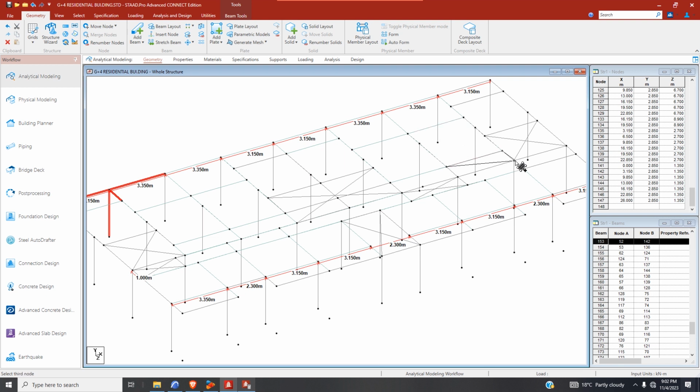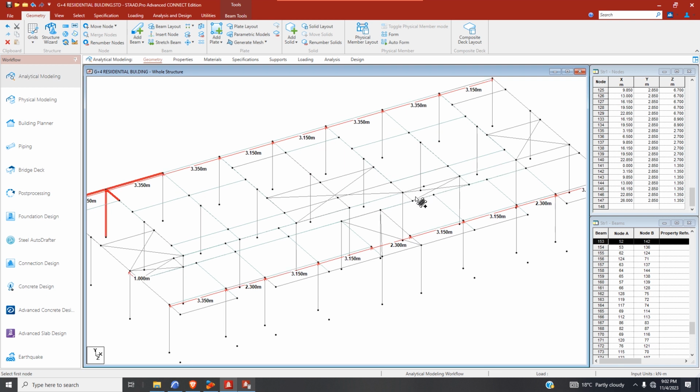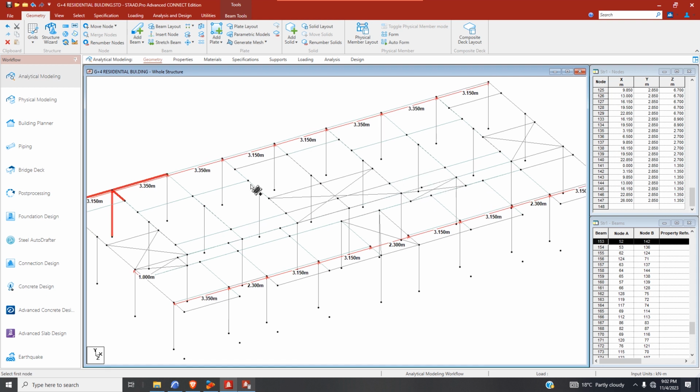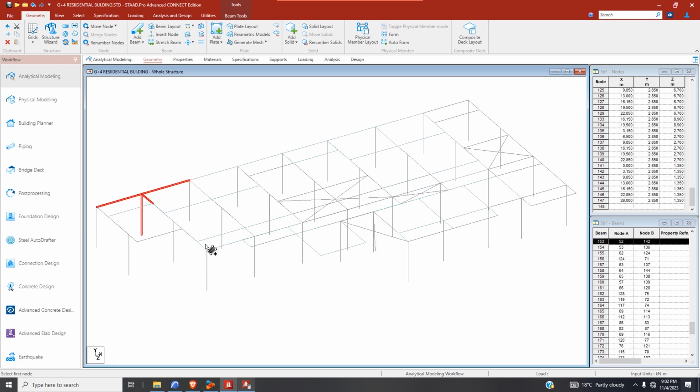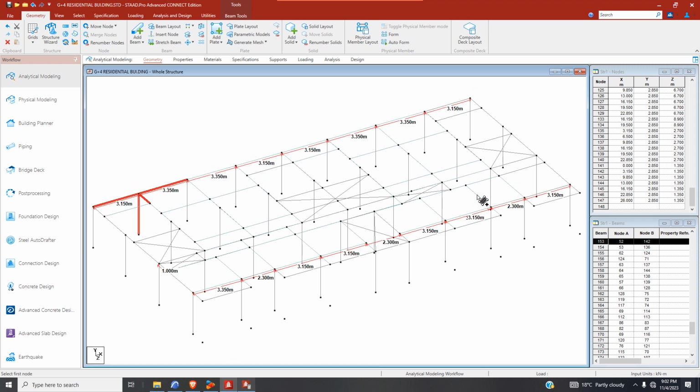Now we have another beam at this point here by how many meters? So just measure from this point here by 4 meters, right? So we select this beam, this, and this, then measure a bit Z by 4 meters. Actually, now in the negative direction, that is 4 meters.